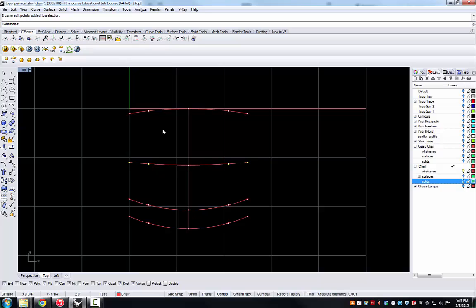let's say for this middle one. I'm going to this time use a scale command, which might seem very odd to scale these, but what it means is I can select a center point and scale these outward by, let's say, 30% by saying 1.3, and they will move symmetrically outward to a 30% line.